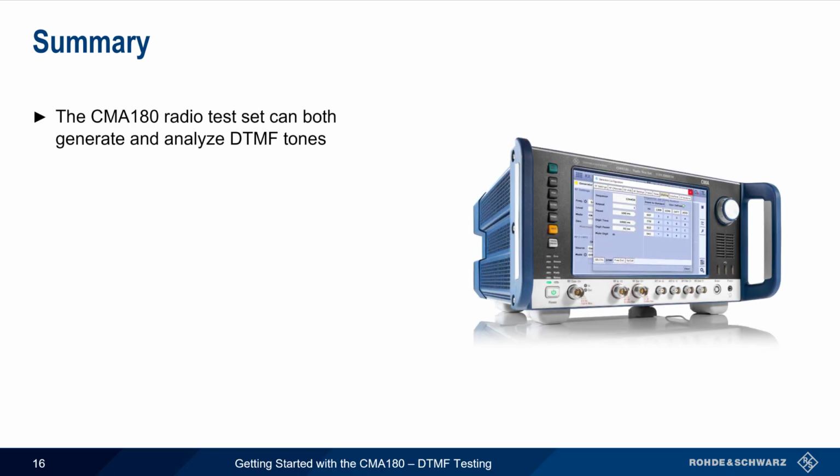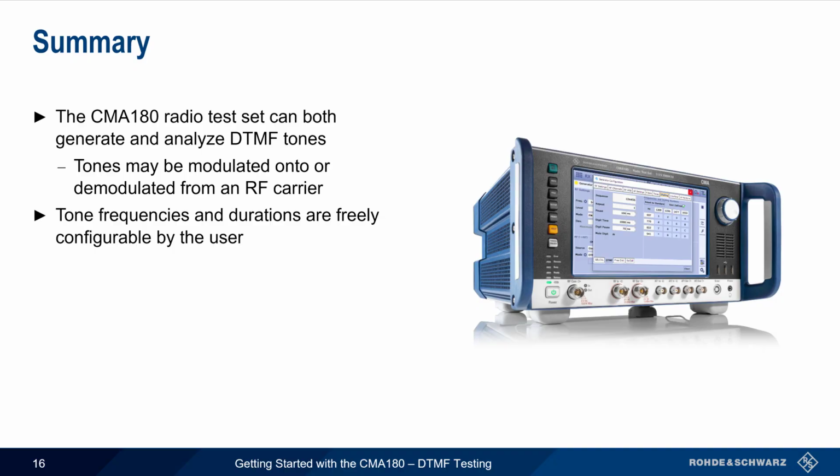Let's end with a brief summary. The Rohde Schwarz CMA180 radio test set can both generate and analyze DTMF tones commonly used in two-way radio applications. In this presentation, we showed how to do this with tones modulated onto an RF carrier. On the CMA180, the DTMF tone frequencies and durations are freely configurable by the user.